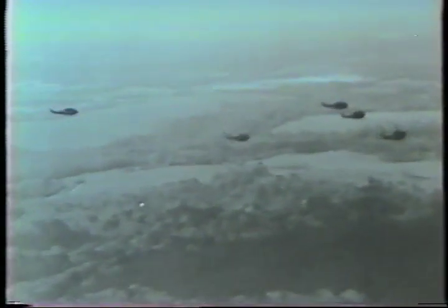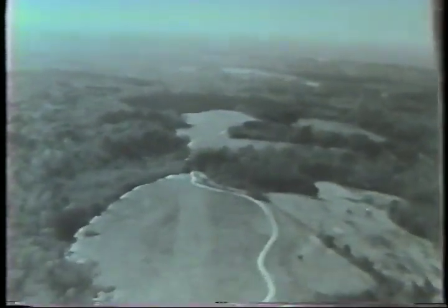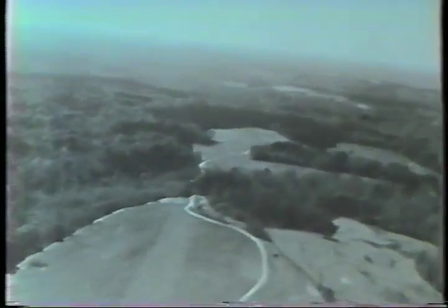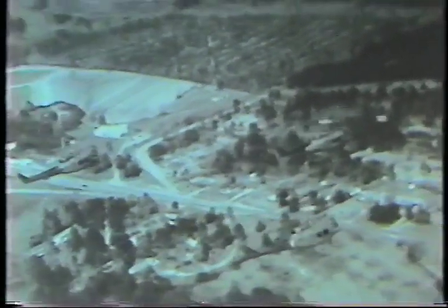Careful planning and judgment must be exercised before departing the formation, especially if the troubled aircraft is located in the center of the formation. The departing aircraft must descend and turn away from the formation. The aircraft assigned to assist the departing aircraft will maintain altitude in the area of the downed aircraft to make necessary radio communication. The possibility of such problems arising and the procedure to follow should be covered in the flight leader's pre-mission briefing. After the departure of a ship from the formation, the flight leader should rearrange the formation to fill the vacancy and continue with the mission.